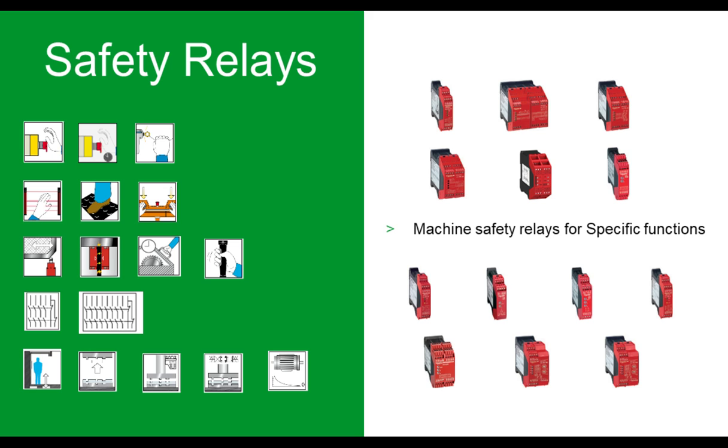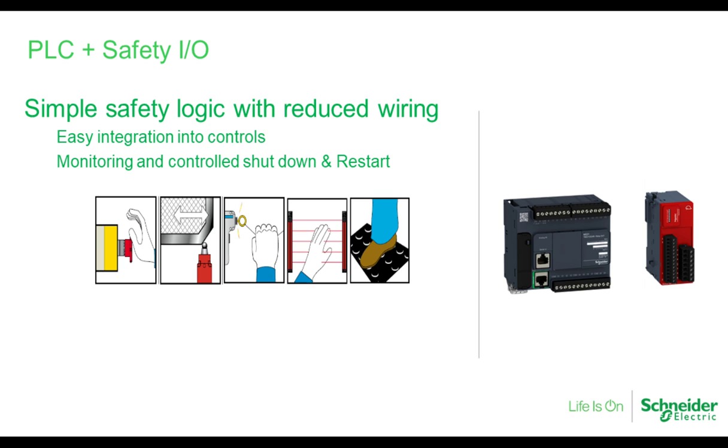I kind of say to myself, if you need 3 or more relays, you probably should have used something like a programmable safety logic controller. But that's just a rule of thumb that I use, because if the complexity gets beyond 2, 3, 4 relays, then doing something programmable is probably going to be less expensive and easier. But most of the time, it's relays that you see in the control panels because it covers most of the need.